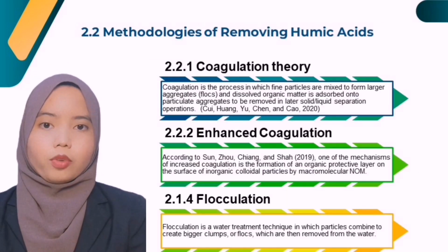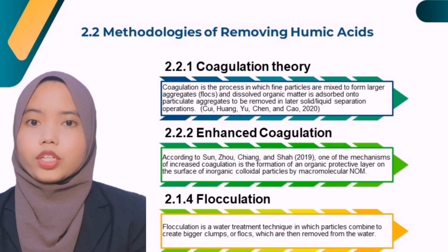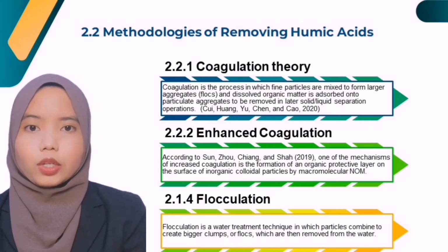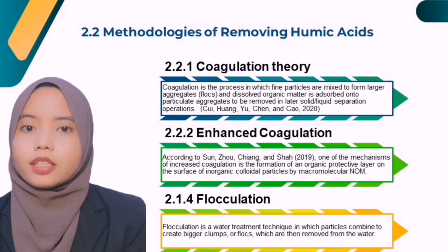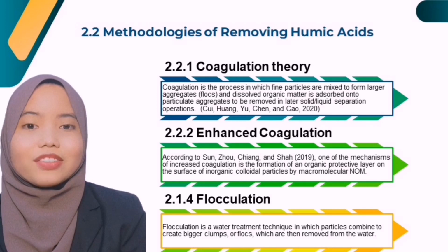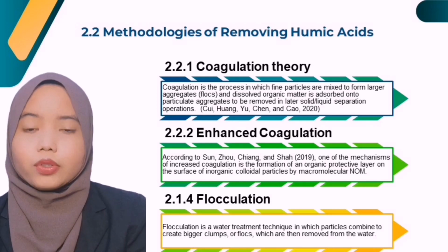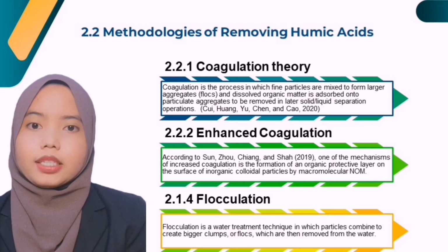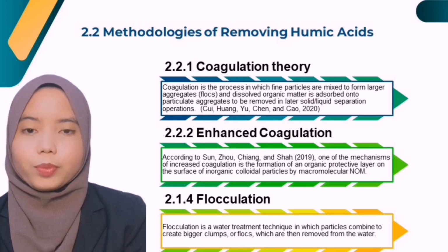2.2 Methodologies of removing humic acid. First, coagulation theory. Chu et al. stated that coagulation is the process in which fine particles are mixed to form larger aggregates, which are called flocs, and dissolved organic matter is adsorbed onto particulate aggregates to be removed in later solid or liquid separation operations. Second, enhanced coagulation. According to Sun et al., one of the mechanisms of enhanced coagulation is the formation of an organic positive layer on the surface of inorganic colloidal particles by macromolecular natural organic matter. Third, flocculation. Flocculation is a water treatment technique in which particles combine to create bigger clumps of floc which are then removed from the water.